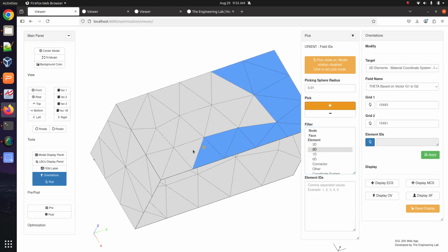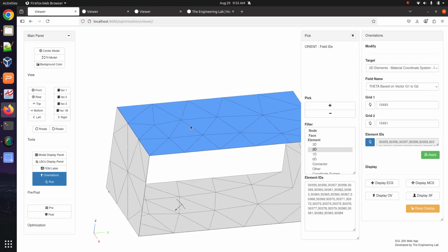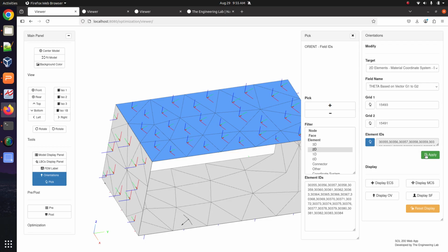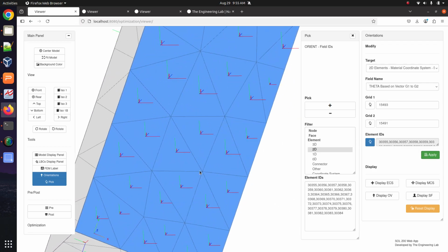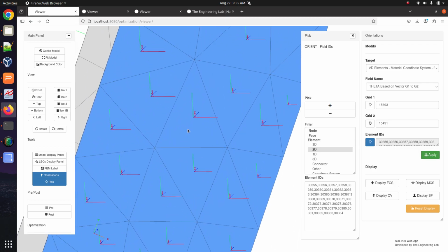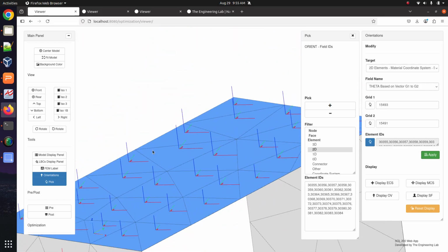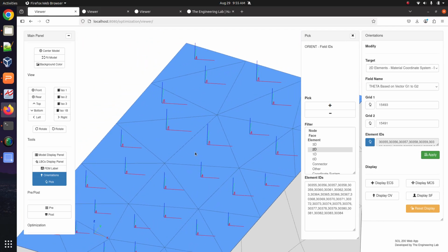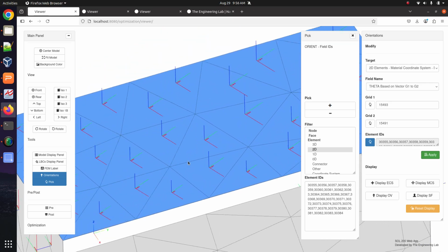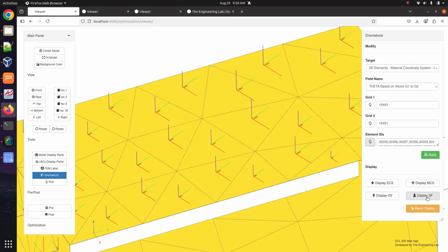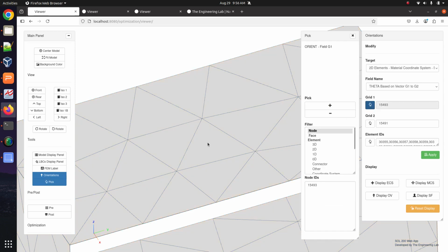And you'll notice that the vector I defined there, those nodes, are not in the direction that I want. But I wanted to prove to you that the 0 degree directions are following that vector we defined with point 1 and point 2. And now you can see that I didn't define the vector correctly, so let me redo this again.